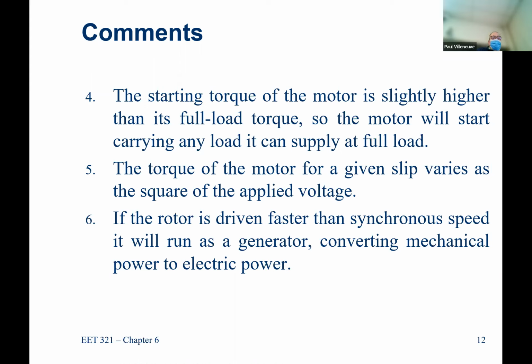Yes, so the question is, do you turn off wind turbines at too high of a speed? The answer is 100% yes. You rotate the blades. A wind turbine is designed with its blade angle of attack to capture the maximum amount of wind.